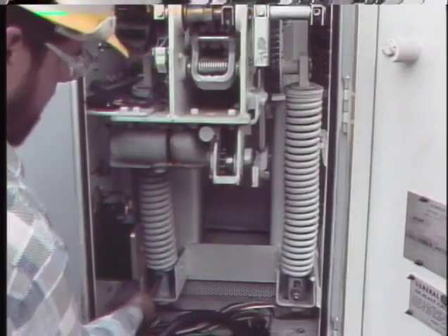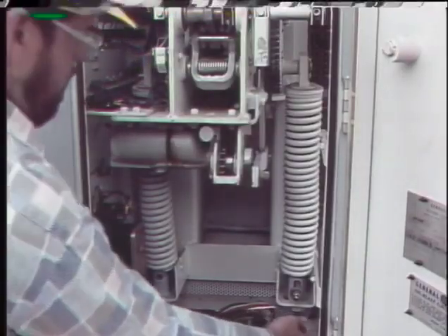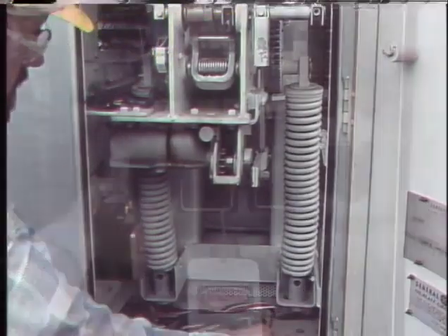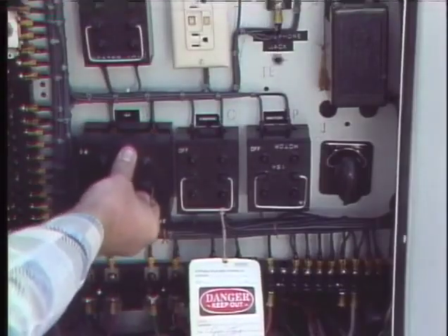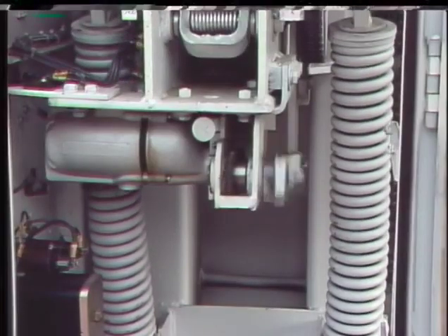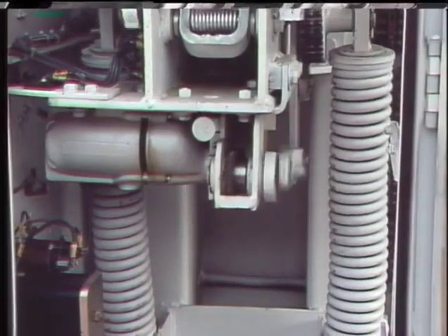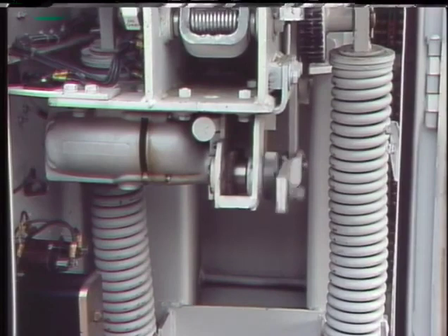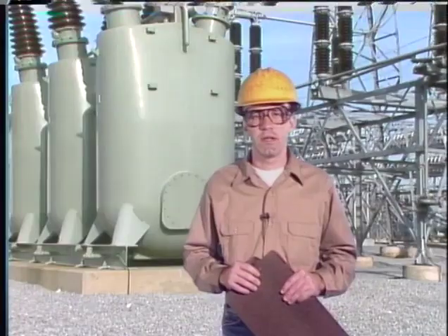The same is generally true for motor spring operating mechanisms. The blocking is removed. The control circuit is energized, and the operating mechanism is electrically operated to see if it works properly. A word of advice is needed here. When you energize the control circuit of a circuit breaker and operate the breaker, be sure you observe your company's tagging procedures.